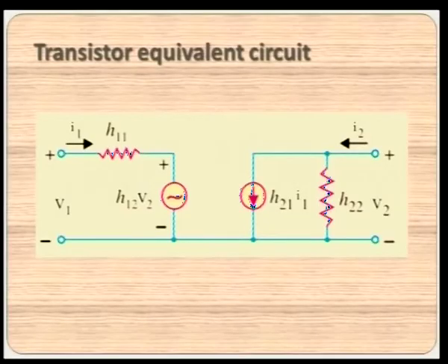And is it possible to develop the transistor parameters for the other modes of operation? Let's quickly have only the circuits, and the H parameters for other modes are also possible. The above equations define H parameters of transistor in CE configuration. The same theory can be extended to transistors in other configurations like CB and CC mode.